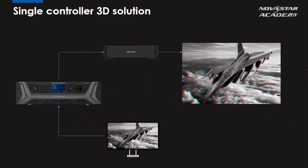So this is a single controller 3D solution. Let's say, for example, we have a screen whose resolution is 1920 by 1080, a standard Full HD screen resolution. If we want to do the 3D display effect on it, we have the 3D controller, which, as we all know, supports 4K. The video source goes out from the PC graphics card through the 3D controller and the EMT200 3D emitter. It's a simple structure for a small resolution LED screen to realize the 3D solution.